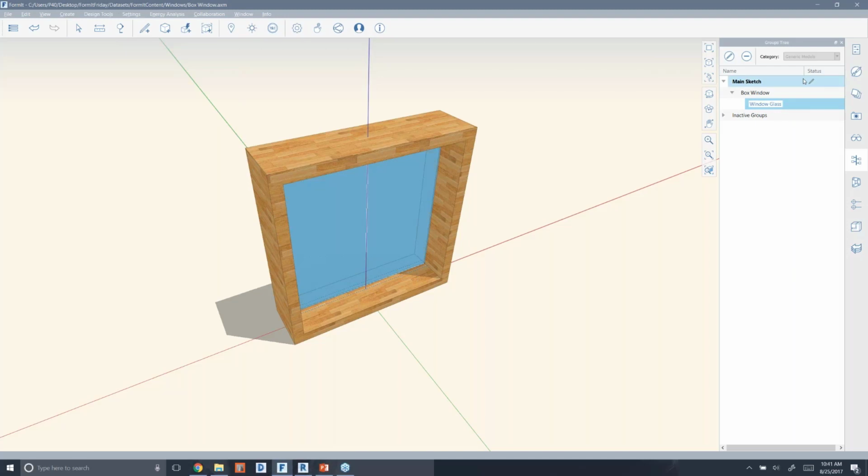And I can double click and edit those. I'll just change this so it's called glass layer. And now I've got that sort of model management setup done. I know I'm going to be sending this to Revit, so setting it to generic is important. If I left it as a mass, I would not be able to import that into a window family category. I'll also check, like I mentioned, the scenes to see if I inherited any scenes with this model, and then the layers. I'm going to go ahead and delete that layer so that I don't have any layers when I import this object in the future.